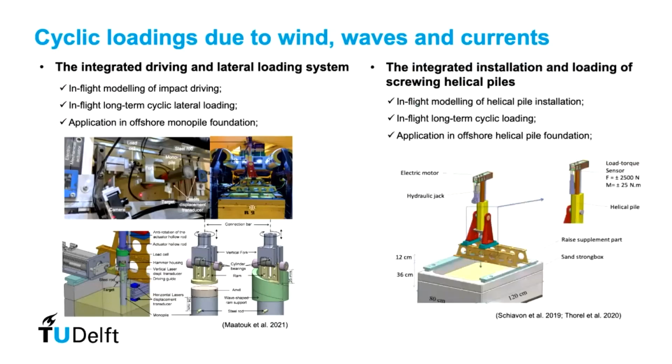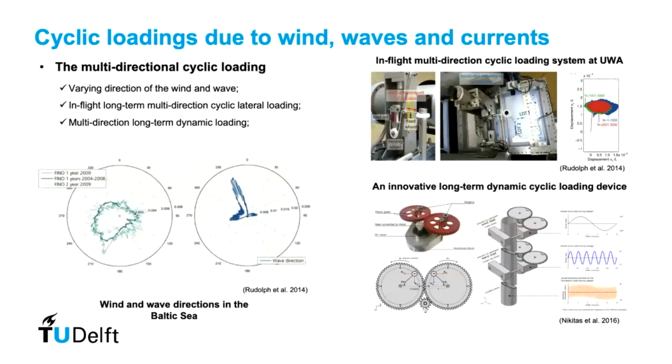There are other capabilities, for example, studying screw piles or helical piles that are quite common in the offshore industry. Here, what people are interested in is how to optimize the driving methods so you ensure that they are very well placed inside and can sustain the loading. Of course, loading from these environmental actions is never one directional. You can have loading that goes in different directions. You are interested in understanding how a collection of piles connected together can behave if the load is applied at a certain angle. And that can be done in different ways.